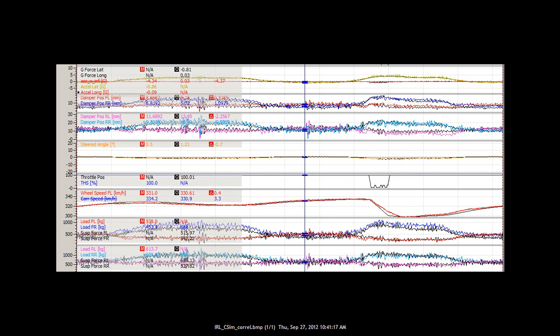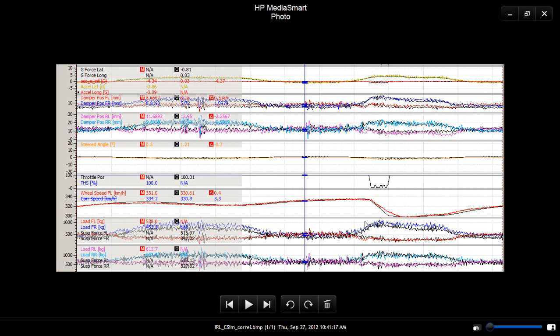The difference is, in this particular zone here, ChassisSim has just overbraked a little bit, where the actual car rotated through a little bit. Now, if you want to, you can chase that. Let me just say one thing very clearly here. If we take a look at the correlation between actual and simulated longitudinal G, there's not very much in it. By all means, if you want to impress team management, you can play with that to your heart's content.